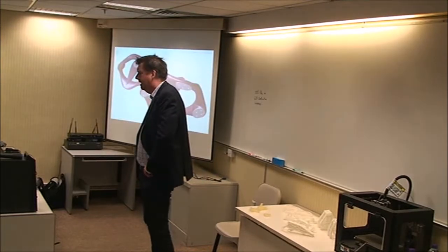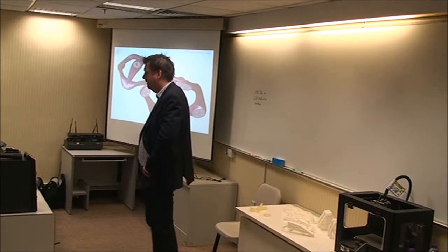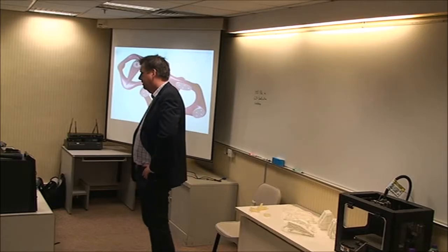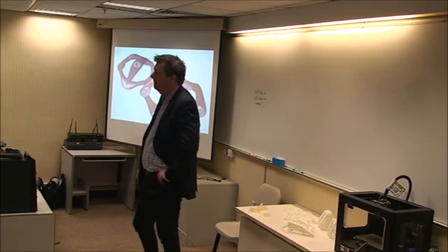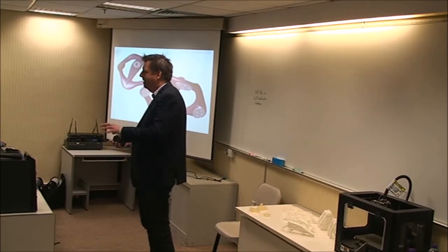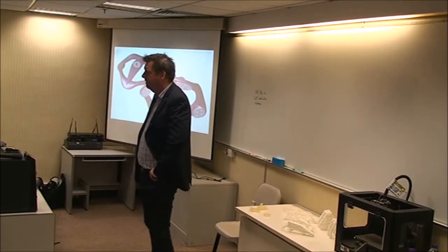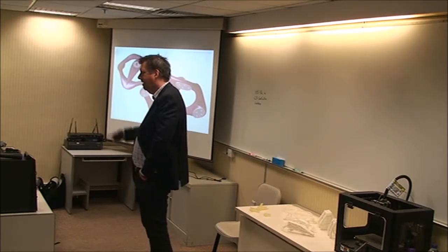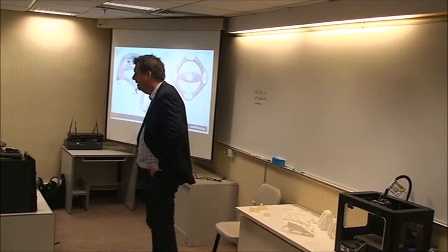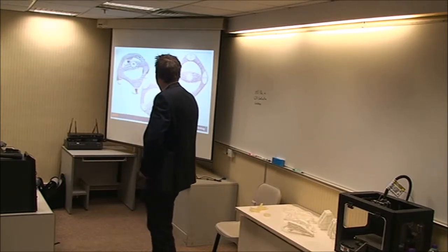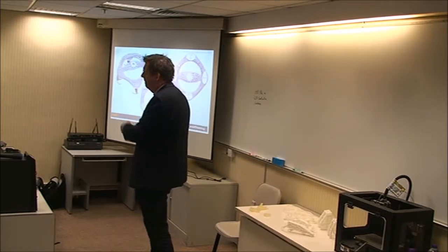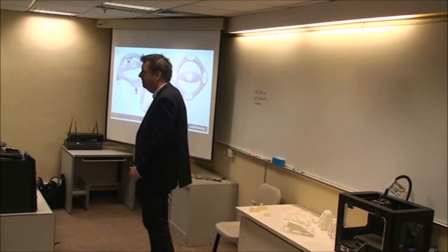This is a facade bracket, so in the architecture example, you've got 4 sheets of glass coming there. So the approach we're now looking at, that we're going to implement in Inspire as of yesterday, is design and non-designable regions. You've got your grey non-designable, turn the entire designable region into lattice, and not the mixed one we saw on that Renishaw example. On this example, all the solid regions remain solid, and all the lattice regions become 100% lattice, if that lattice is optimized.